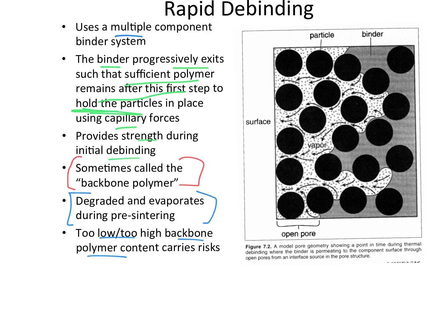And you have to do enough of it because you want your compact to have the critical strength it needs. All these things have to be taken care of. With ceramics, zero carbon is tolerable, because in ceramics, the carbon will sit there at the grain boundary, and it'll just be like